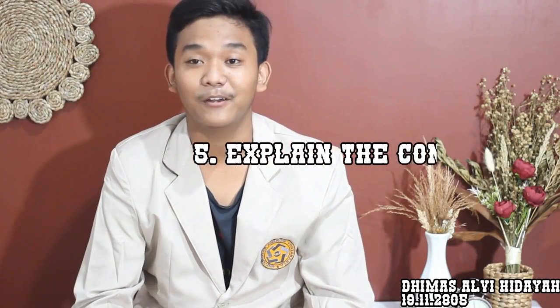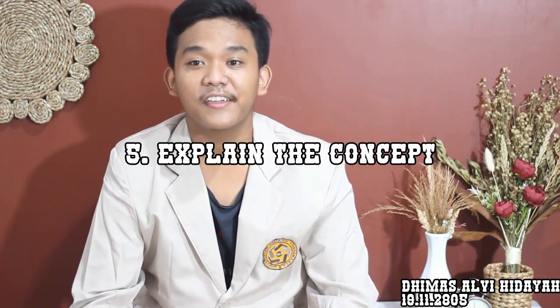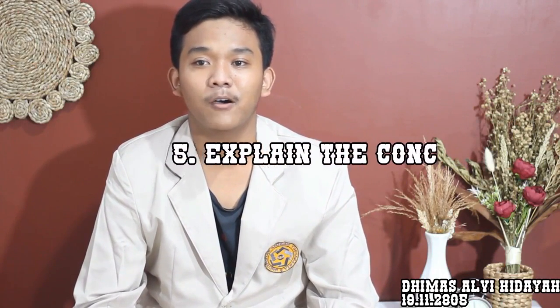Bismillahirrahmanirrahim. Assalamualaikum warahmatullahi wabarakatuh. Here I will explain the concept of the Arduino program that we use in digital input. We use 3 LED lights, a button connected to the ground, and a resistor. If the input is high, then it is not depressed. If pressed, it will become 0. It becomes the depressed status for digital input.